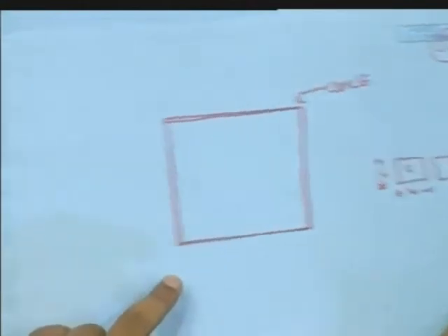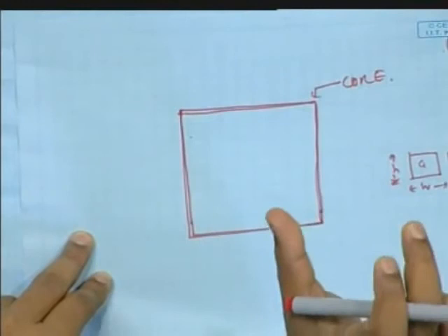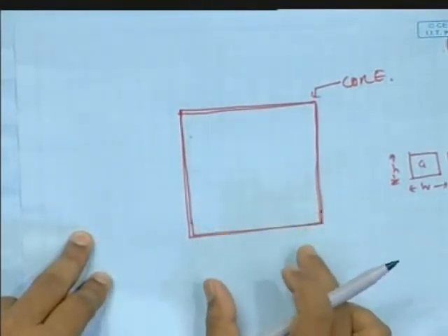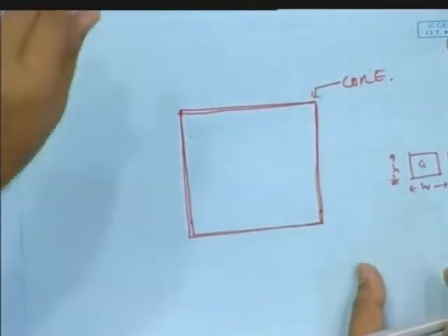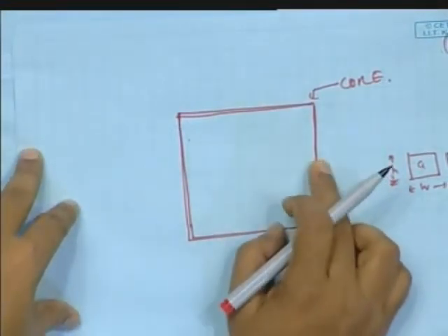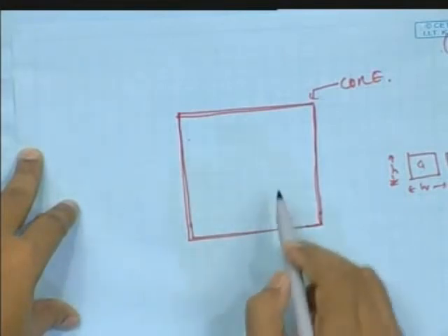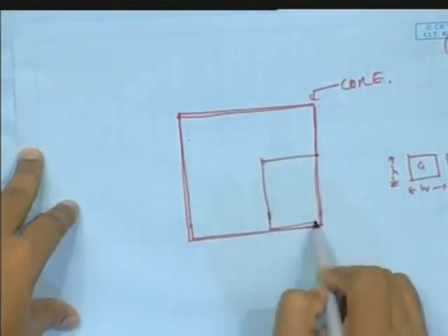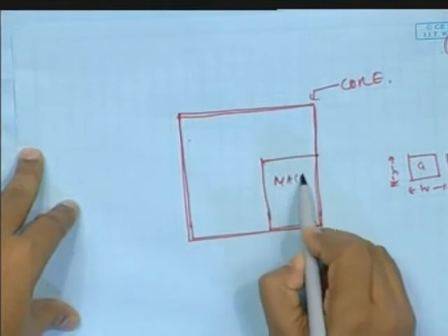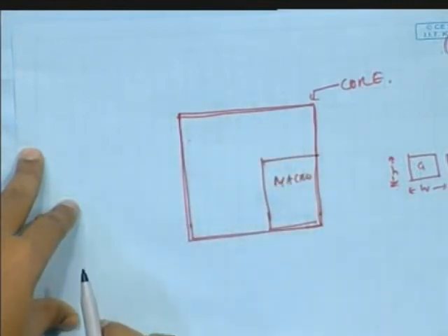I have to place cells as well as macros. Macros means, say, an FFT block that one particular company gives you, which you directly hook up. Macros need handcrafted placement; you place it here, say, this is one macro. In the remaining place you can place these standard cells.